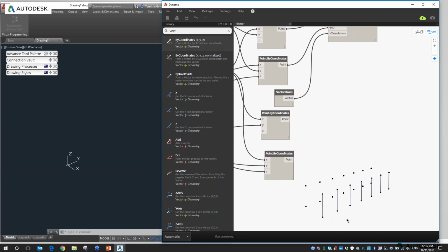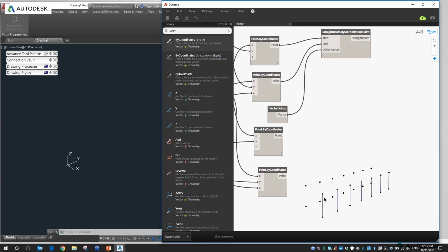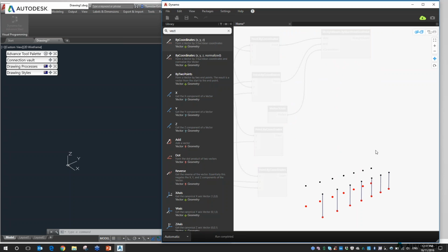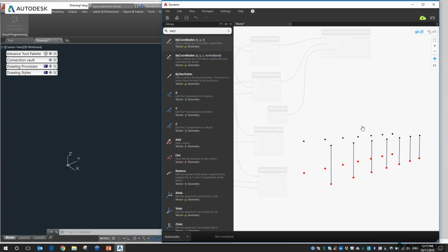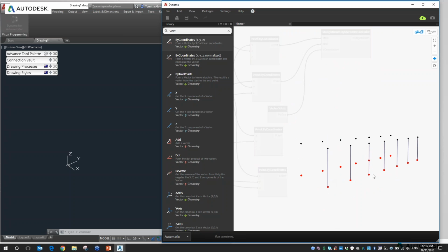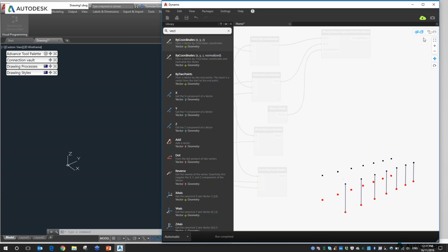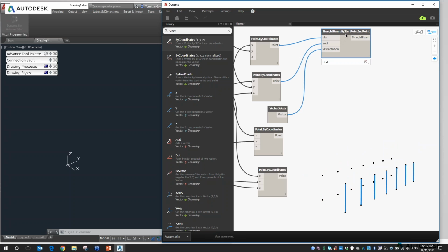Once we've orientated it, we haven't denoted a beam yet, but we do know that Dynamo is going to draw a beam between this array of points on our ground level, for example, up to the height there. I'll switch back to my programming and copy this down. To remove connections, you just click on it, and I'm going to keep the vector one there because that's common between the two. Now we're going to do the same thing for the other side of the bay. One point, other point, and there it is.